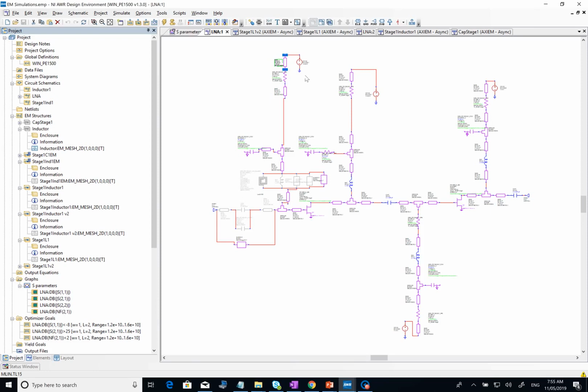It has to come as a separate port from outside in one EM. But when you do that, you might run into problems like having a different S21 curve to what you originally had. So that's why I suggested doing EM simulations for example the cap separately, this inductor separately, and this cap separately, and then you do a full EM for this section afterwards.